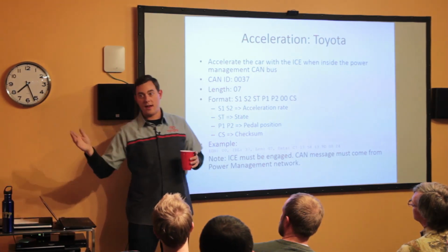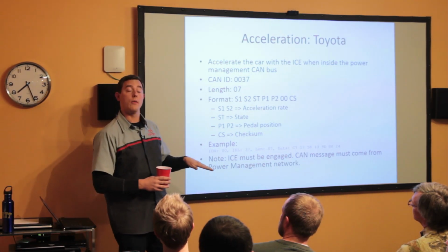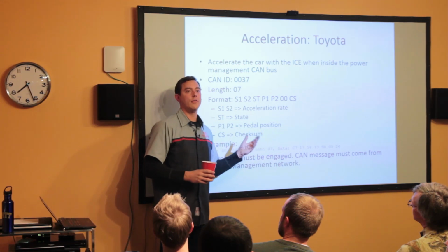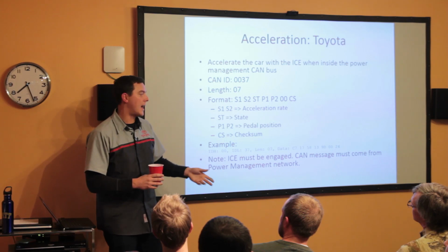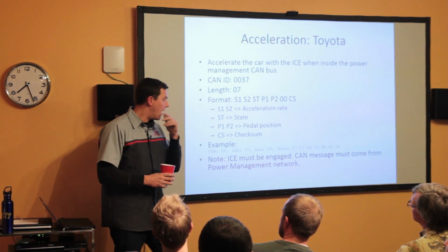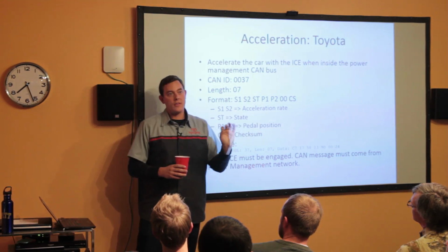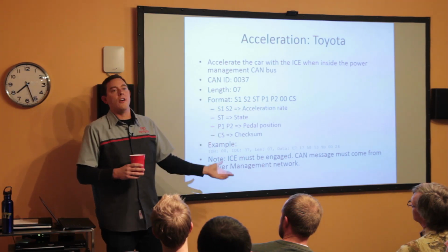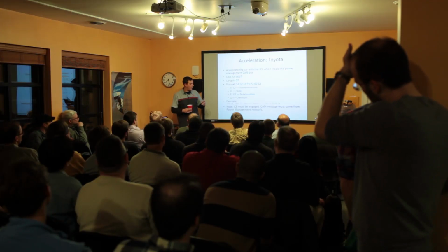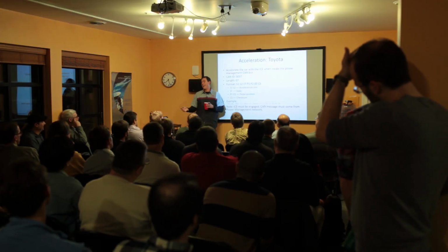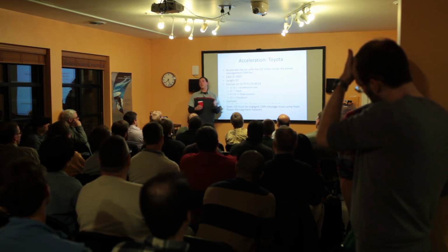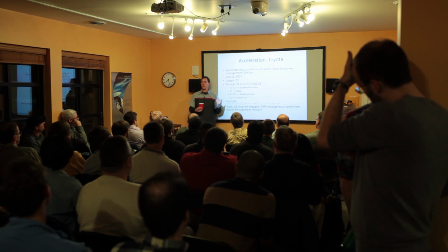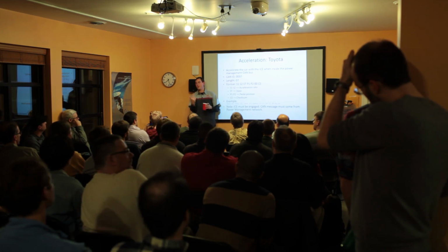in between the bus, and I could send messages saying, hey, we're at the floor, right? And the car would accelerate itself if the internal combustion engine was activated. The moment it activated, you accelerated. We did this because it was a bit segmented. If you owned a car, you would own this ECU anyway. But we wanted to show that you could also just jack in. So if there are any exposed CAN wires on a car, you can just put two little alligator clips on them.